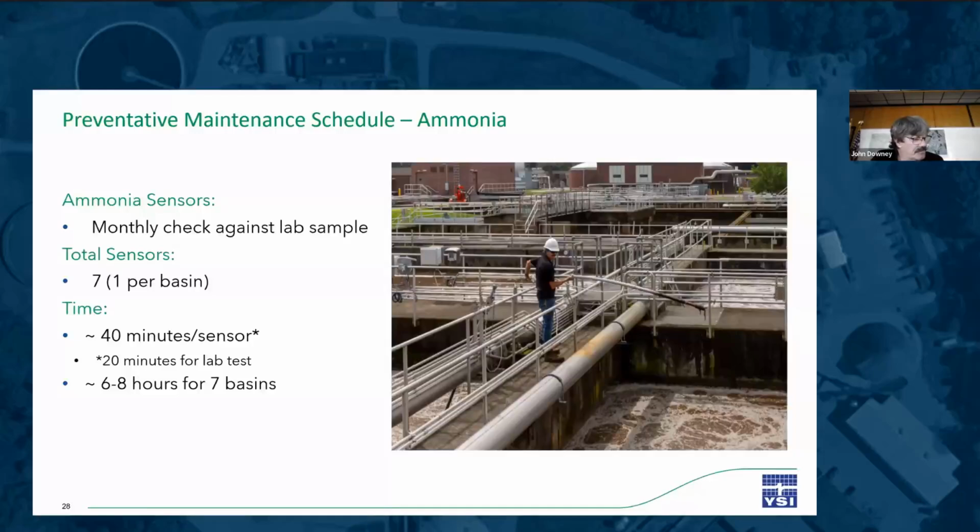The 0 to 2.5 parts per million range test allows us greater certainty about the concentration of the grab sample. The other requirement is to filter the grab immediately. This is because the concentration of ammonium can change rapidly and skew your results.